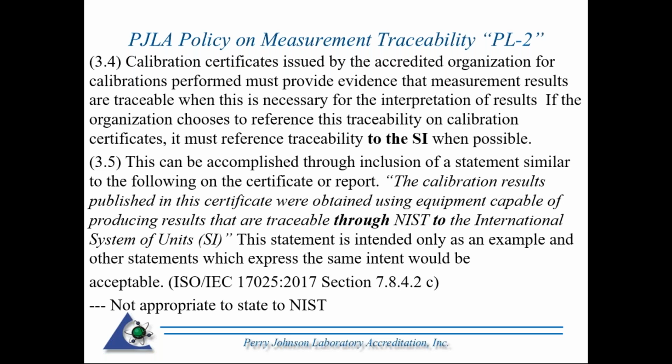I used to see it quite often, not as much as when I was doing assessments. A lot of folks like to say in the U.S., we're traceable to NIST, where our measurements are traceable to the National Institute of Standards and Technology. The folks at NIST caught on to that and do not like to see that. It's not correct. Basically, you are actually traceable through NIST, or the NMI if you're coming from another country, through your National Metrology Institute to the SI units.